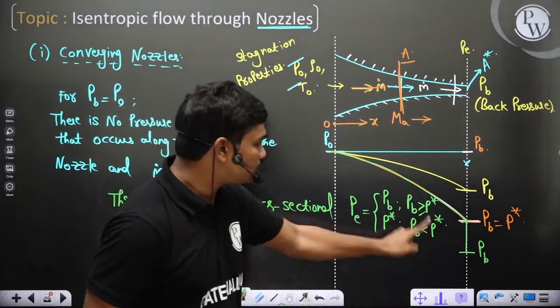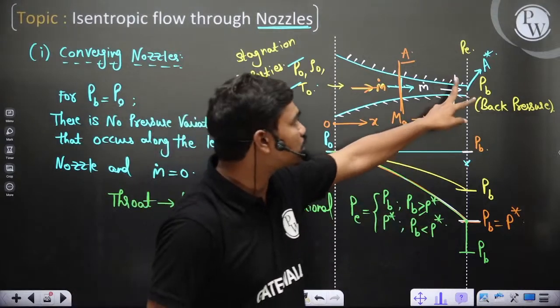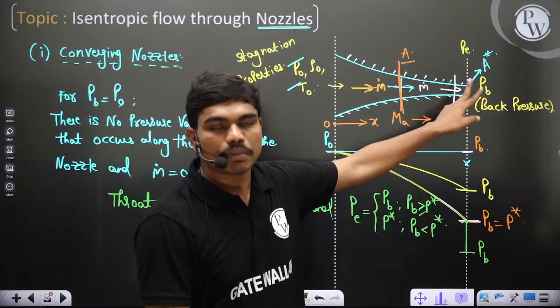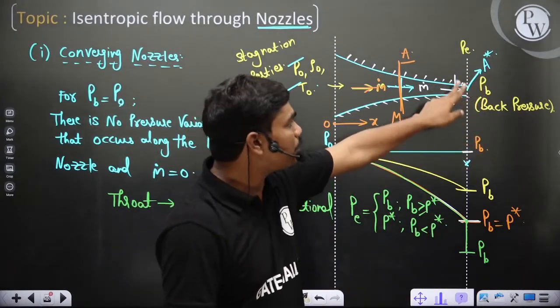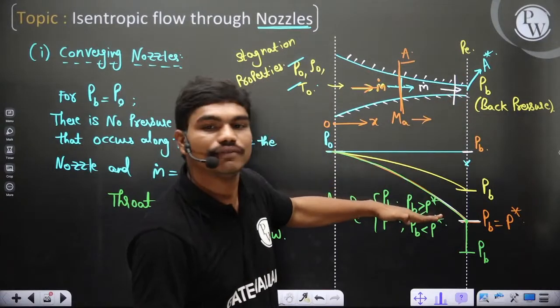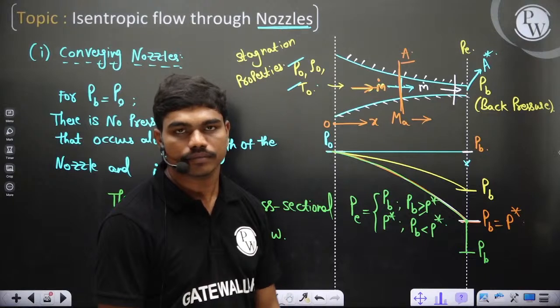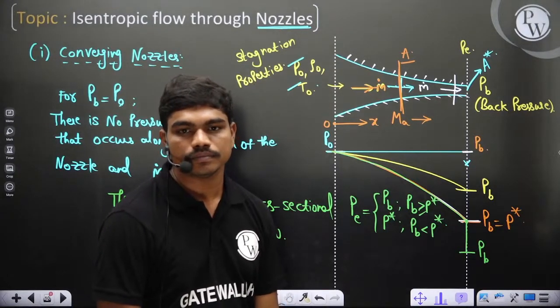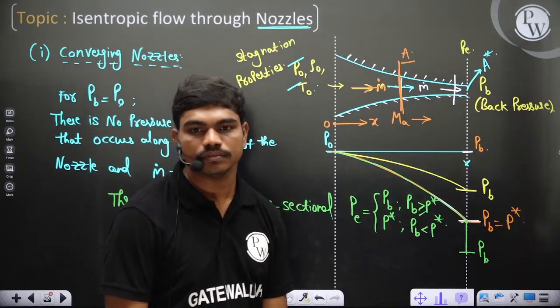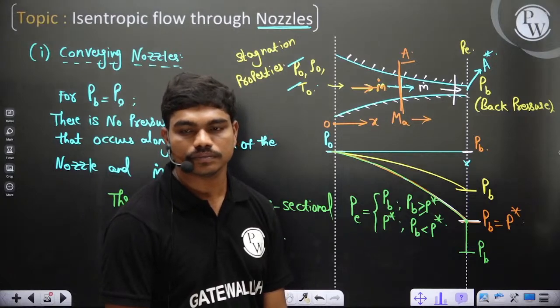Now did you understand the difference between these two? Because initially when I'm telling these two are two different pressures, there could be some confusion, but actually these two are not the same. Okay, they appear to be the same only until this condition where PB is more than the sonic property or sonic pressure at that situation. Clear to all of you? Yes or no?